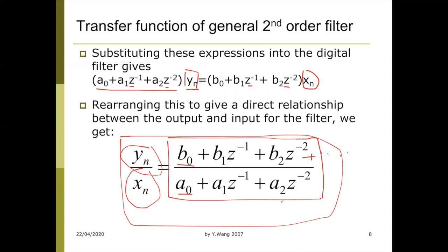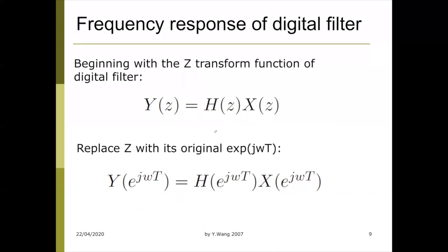By doing that, you can derive the frequency response in analytical form, because Z in the frequency domain is equal to e to the power of j omega T. This is how it is defined. It involves e, the base of the natural logarithm, which is a constant like pi, roughly 2.7. j is the imaginary unit, a complex number. Omega is your frequency in angular form, equal to 2 pi f. T is your sampling period, 1 over fs. Again, it's still complicated. That's why we don't directly use frequency-based expressions in digital filters. We encapsulate it in this factor Z.